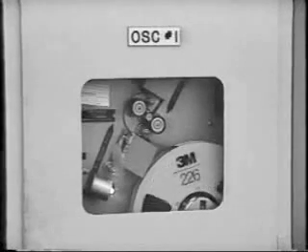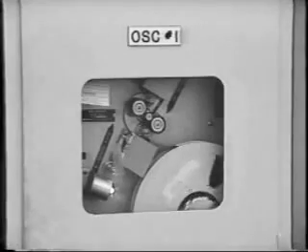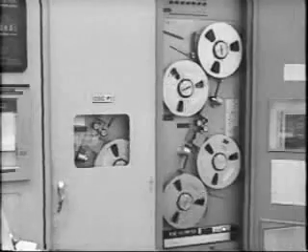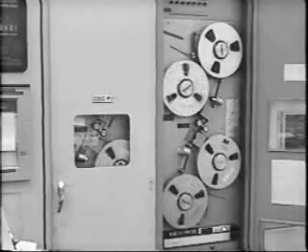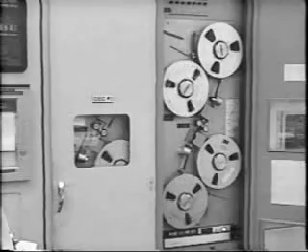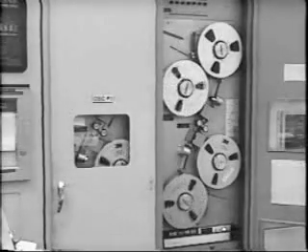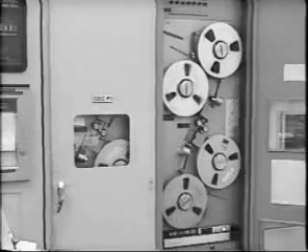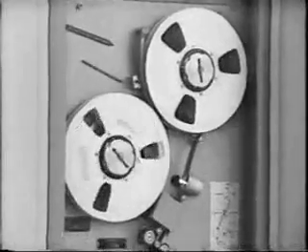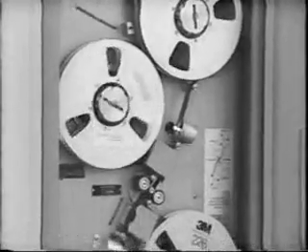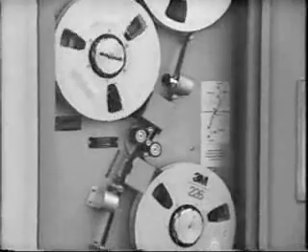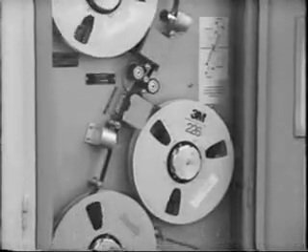A third type of fault recording machine is the continuous oscillograph. In contrast to the quick start and pre-fault recorders, this machine does not need to be started by a fault or disturbance, and it also does not use paper. Instead, it continuously records system conditions on reusable magnetic tape.